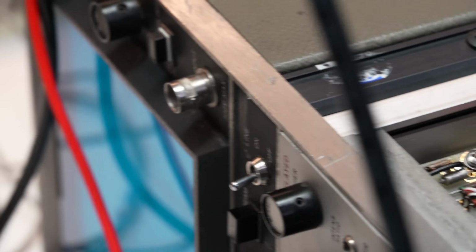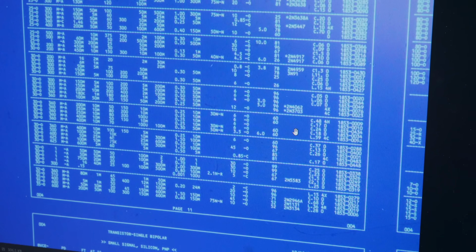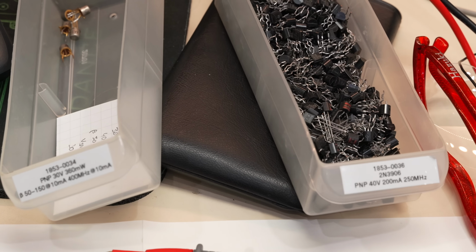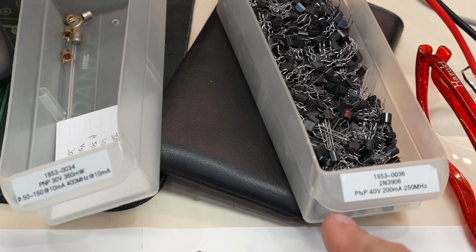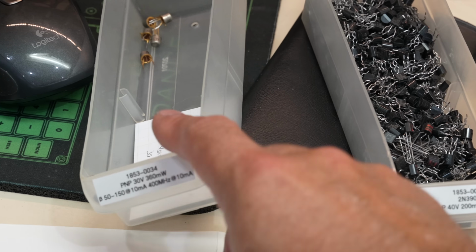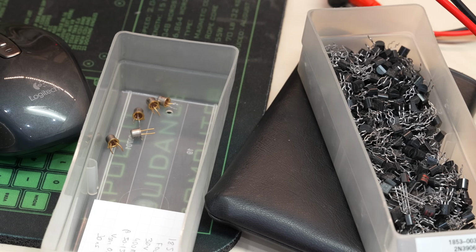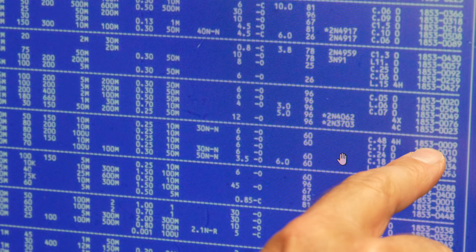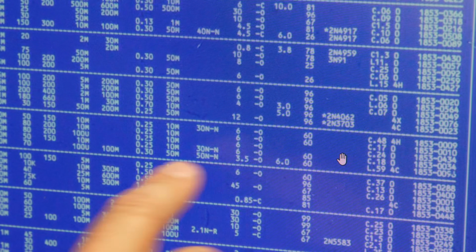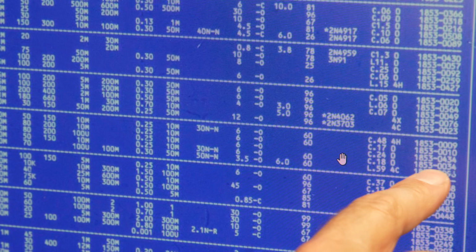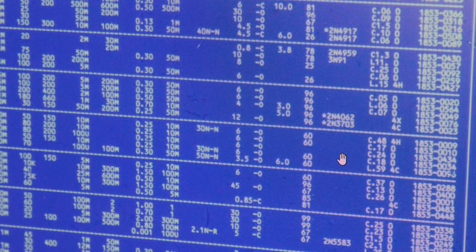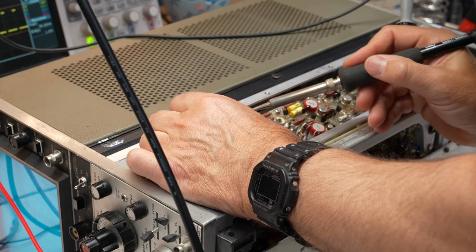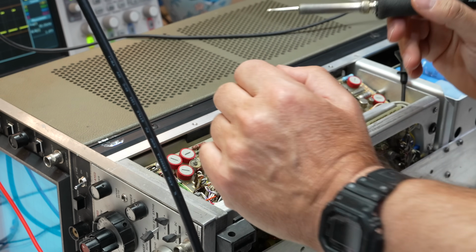And of course, the other proprietary transistor, another one that's in my fiche, and it's a current source, so you don't need very much. So I could replace it with a 2N3906, but I have an HP transistor that's exactly the same, except it's a little faster. This one, that's the 09, and I'm replacing it with an 034. That's a few lines down there. It's all the same parameters. It's almost identical.